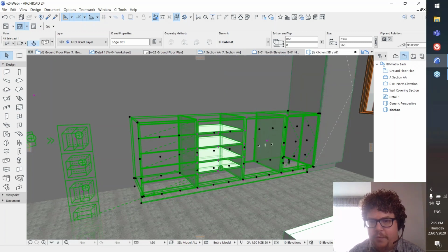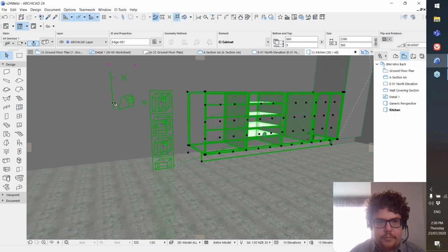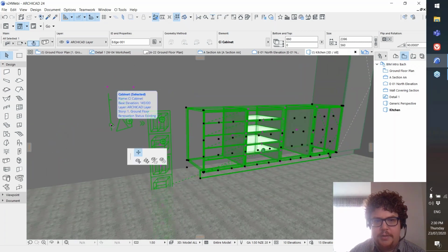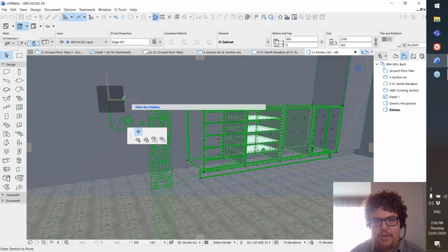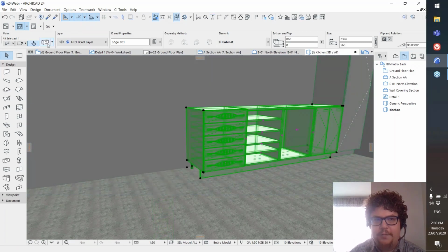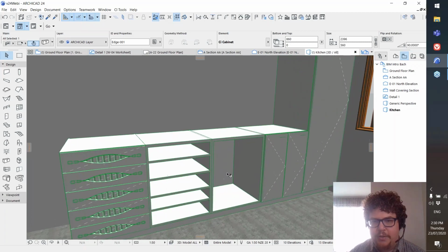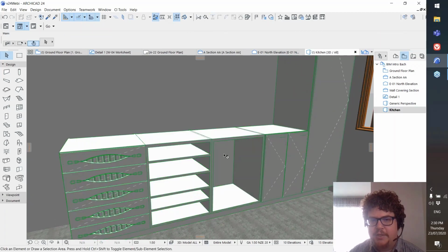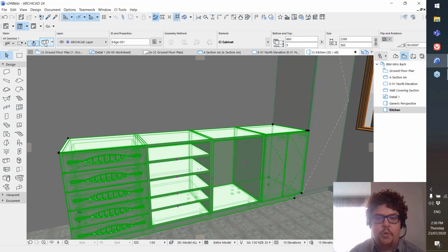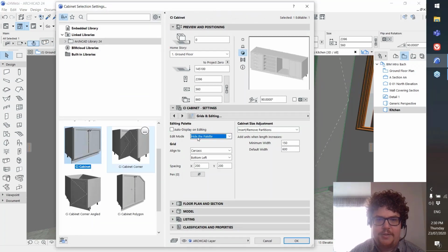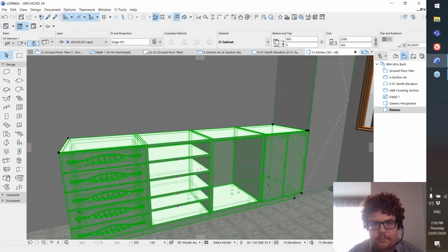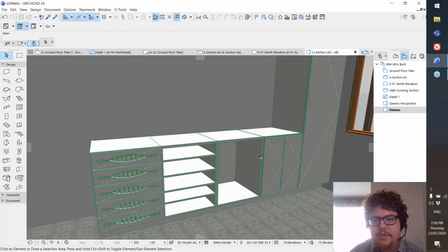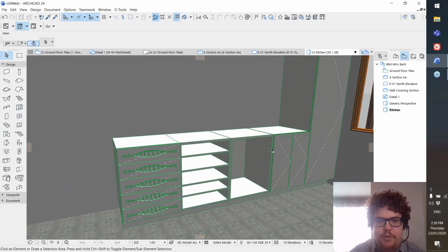And they don't need to be an open front one. You can put them in any. I just did it in this case so that you can see it as I go. And then once you've done, in your edit mode, select this and drag it to the X there, and that will turn the palette off, which will put us back to the constructed mode so that you can see what the actual effect of that change was. Or you can go into edit mode here and set it to hide the palette manually. Either way will work. And so using those controls, you can make a lot of changes in 3D to whatever you might need to with this cabinet.